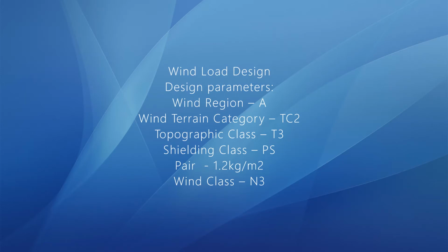Wind load calculations. The wind load is calculated based on AS 4055. Included in this was the method of calculation for wind design of the structure. The external wind pressure of the structure was determined first, which was based on the density of the air and the pressure coefficient. Wind load calculations are important in determining the load combinations of the structure.